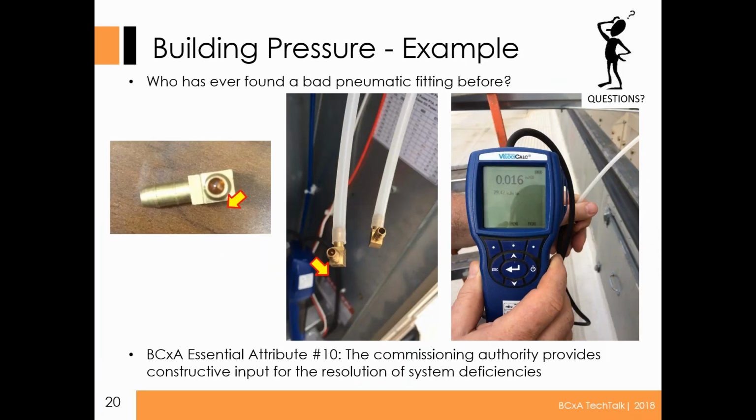This was the actual control panel here, and with some of our issues, that west unit actually had a failed pneumatic fitting. It was this elbow piece right over here that had failed. It was actually clogged. The elbow was not hollow from one side to the other. That was driving us completely crazy for a while.